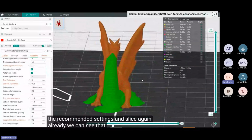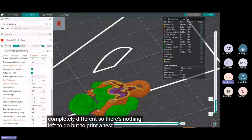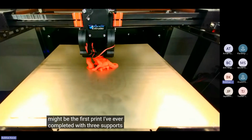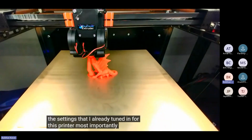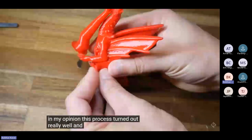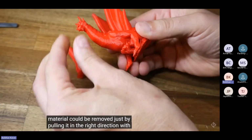Already we can see that this looks completely different. So there's nothing left to do but to print a test to see how easy it is to remove. Fun fact, this might be the first print I've ever completed with tree supports, but I used the settings that I already tuned in for this printer, most importantly the Z air gap between the interface and the model. In my opinion, this process turned out really well, and most of the support material could be removed just by pulling it in the right direction with my fingers.